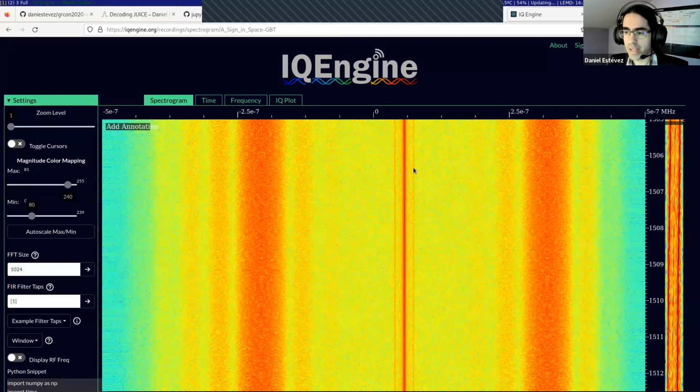And it also makes the signal easier to spot in case there is some problem with the spacecraft transmitter. Maybe the antenna is pointed away from Earth. Still, we have the carrier, which is easy to detect on the spectrum. And then we have the data, which is here and here. These are called subcarriers. Subcarriers are used to push the energy of the modulation away from the central residual carrier so that the digital information does not interfere with any attempts to synchronize with this subcarrier.